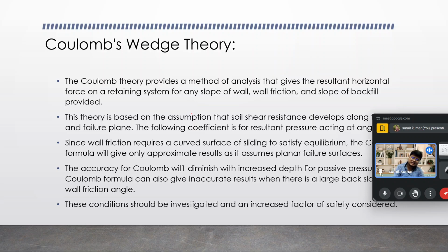So we will move ahead, and we find that the Coulomb wedge theory provides a method of analysis that gives the resultant horizontal force on a retaining system for any slope of wall, wall friction and slope of the backfill provided.